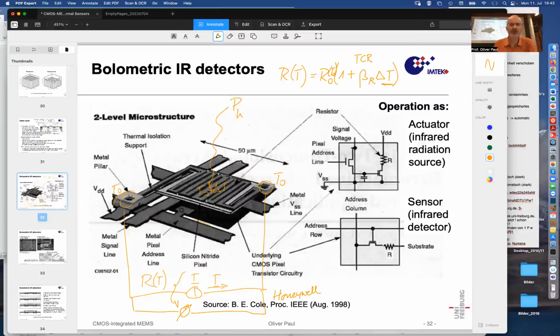to be detected, and then you need to switch on one pixel after the other to determine what its own delta T, or I can also write this as R0 plus delta R. So R0 times beta times delta T is, of course, delta R, its own delta R, not delta R0, apologize. So to determine what its own delta R and therefore its own delta T is, and therefore its own heating power, and therefore the temperature of the object out there at its corresponding location.